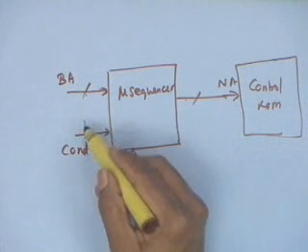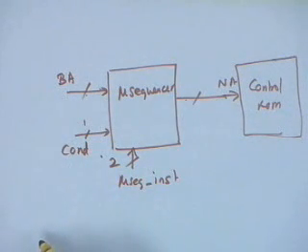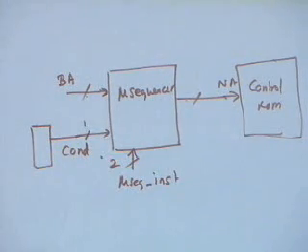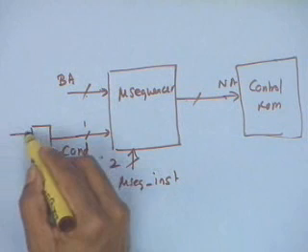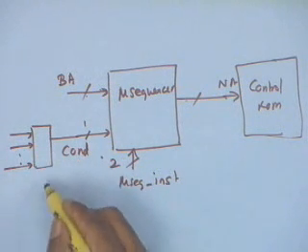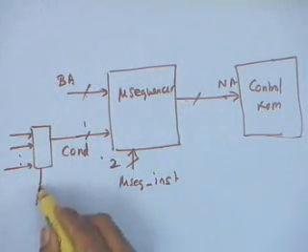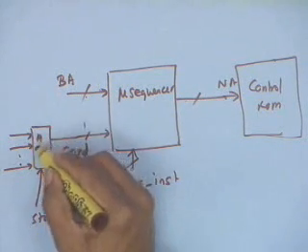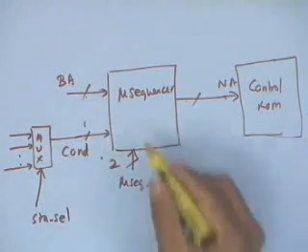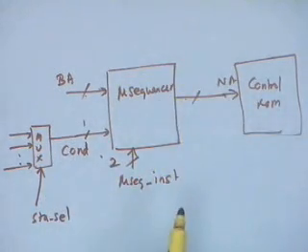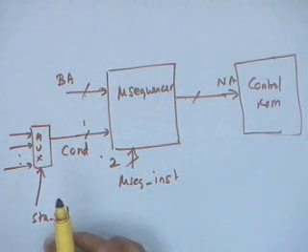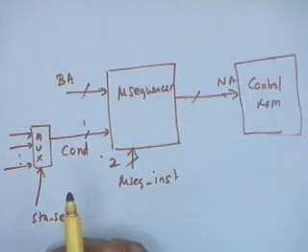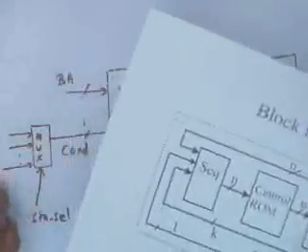This depends, of course, this is just one condition. I will do the multiplexing, I am doing it outside. You can also consider it to be inside or outside, but here I am doing the multiplexing. And the size of this is the number of status lines. I need to do a status select. There is a multiplexer, and this I will get as a condition which is going to be the input to this. If you now look at the overall block diagram and try to understand these things before we start designing the microinstruction format itself.